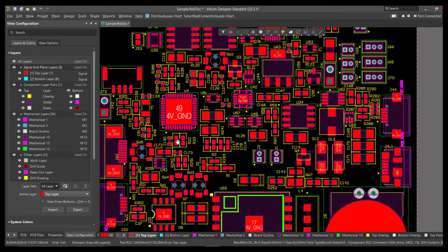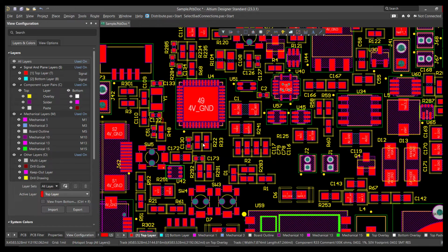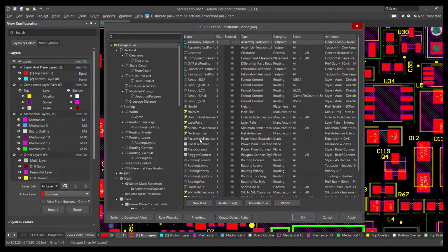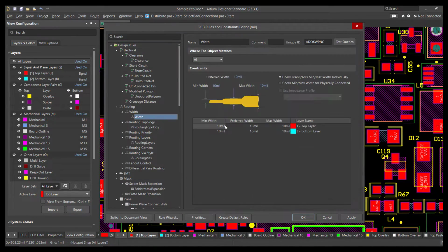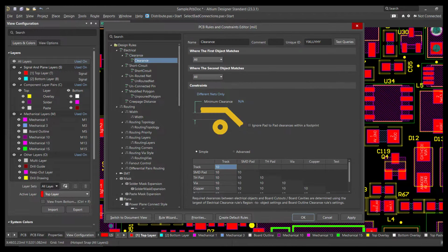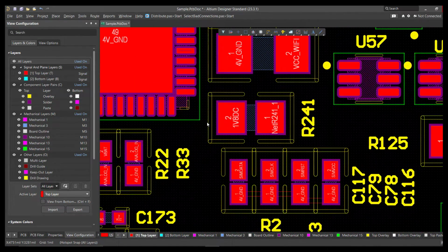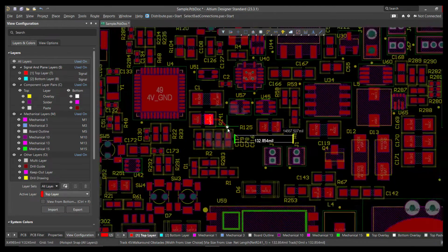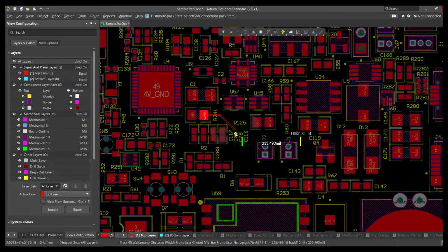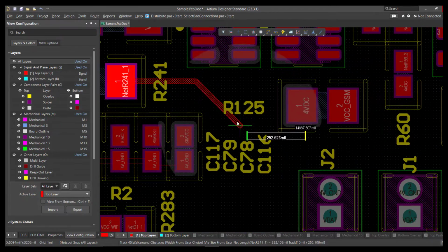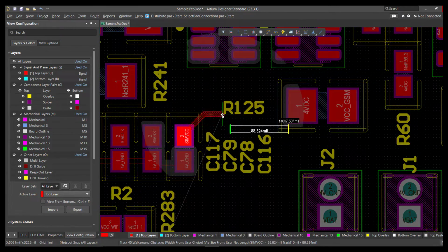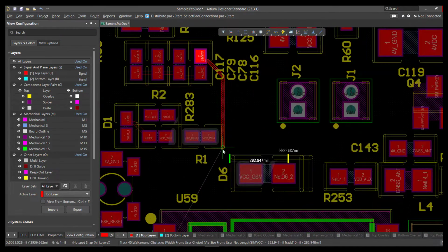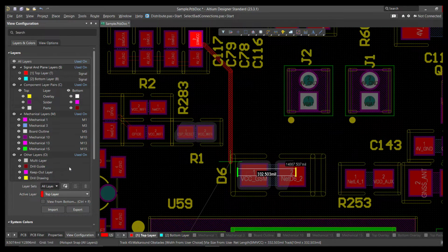Now, if you consider the trace width of the track you'll use in routing traces, it is set in the routing width design rules. Similarly, the considerations for clearance are set in the clearance design rules. The way the interactive router interacts with existing objects like pads and routing on the other nets is determined by the current routing conflict resolution mode. This mode dictates whether the router will walk around the obstacle, attempt to push it, stop, or ignore it.